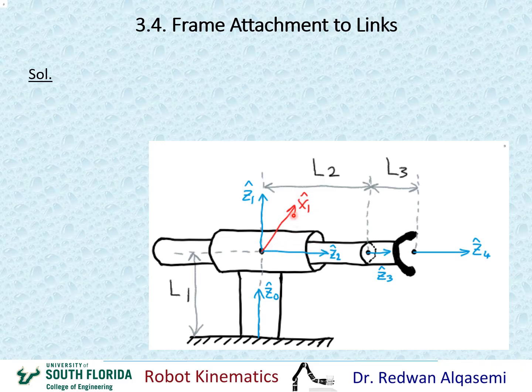So I will draw it initially here similar to x1. So x1 and x2 are the same line, the way you see it right now. But as soon as joint 2, which is a prismatic joint, starts moving, x2 will depart away from x1 and move either forward or backwards, depending on the motion of that prismatic joint. All right, so that's my x2.